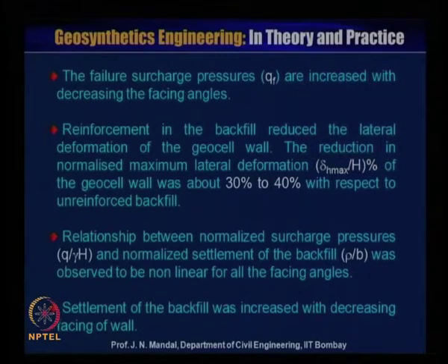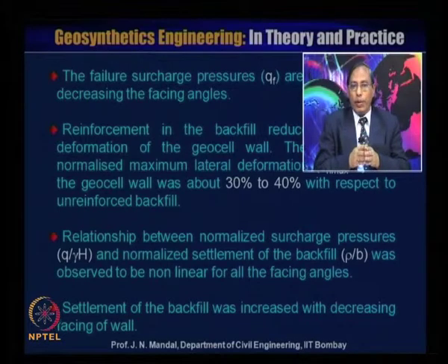The failure surface pressure, QF, increases with decreasing facing angle. Reinforcement in the backfill reduces the lateral deformation of the geocell wall. The reduction in normalized maximum lateral deformation, delta H max by H, percentage of the geocell wall was about 30 to 40% with respect to unreinforced backfill.